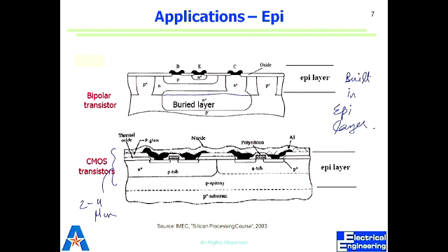Too many collisions with the charge carriers. So we have to control where we want what kind of doping. There is a compromise in doping. You have to see the mobility plot. It will tell you a range above which it starts becoming worse. But you want it heavily doped for enough charge carriers, right? But not in the channel.